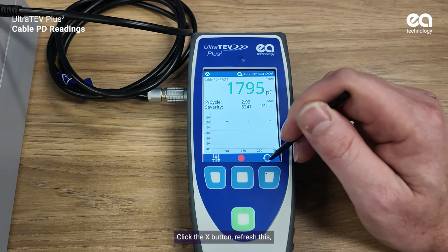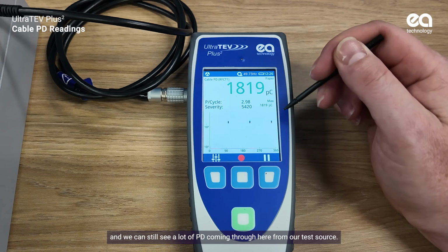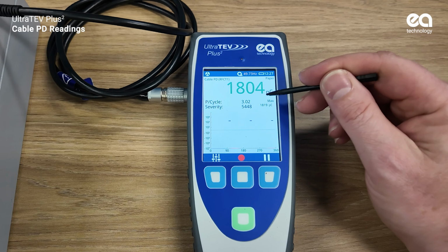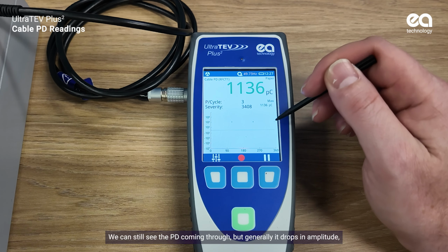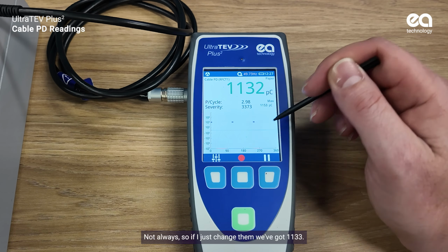Click the X button, refresh this, and we can still see a lot of PD coming through here from our test source, and that's because there must be a big component above 500 kilohertz. If I then change my filtering to 1.8 megahertz, hit the X, again, we can still see the PD coming through, but generally it drops in amplitude. May not always.